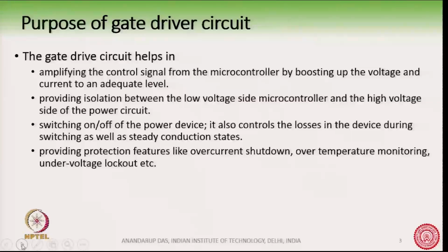Also, these IO pins are probably around 3.3 or 5 volt output, and the gate driver requirement for the power devices will often ask for a 15 volt supply.